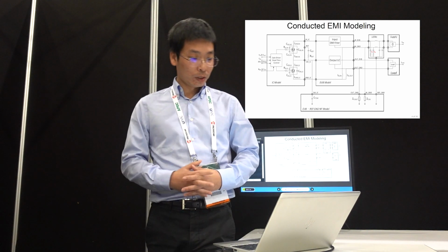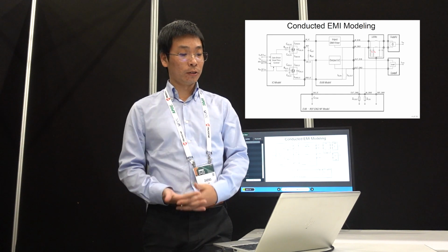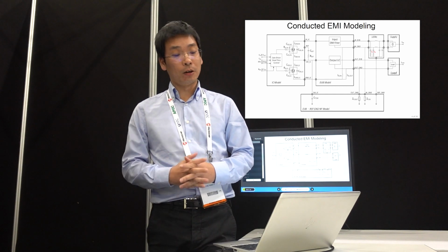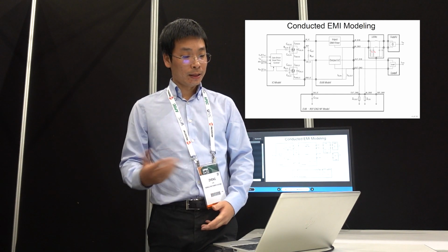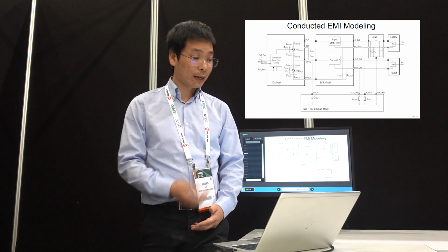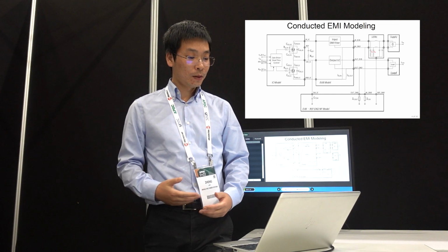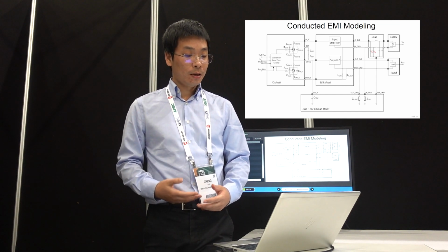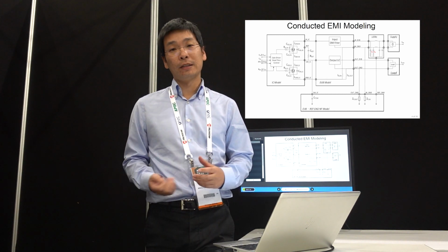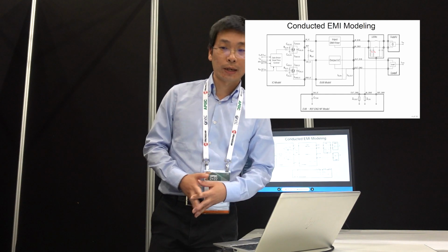And further to the right is the LISN. You can also easily get a model from CISPR 25 or another standard. Basically, it's just a 50 ohm impedance. And after that is the Vin power supply, and you also have your load, which is connected to your PCB board. On the bottom is the parasitic for the common mode noise, basically the parasitic cap from your board to the earth ground of the EMC chamber, and we extract that number from our EMC lab.